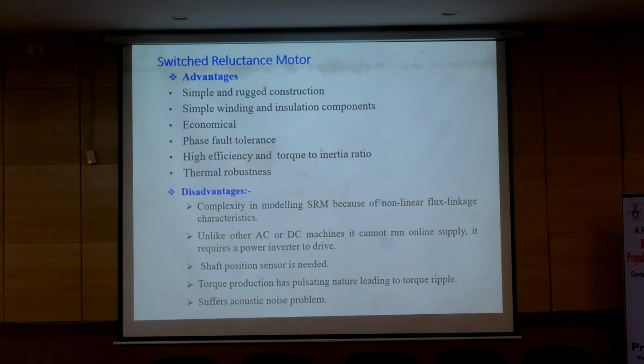The disadvantages are that the modeling of this machine is very complex, because of the flux linkage behavior with respect to the phase currents. They are non-linear in nature. So because of this non-linear flux linkage characteristic, the modeling of this machine is not that straightforward, but quite complex.